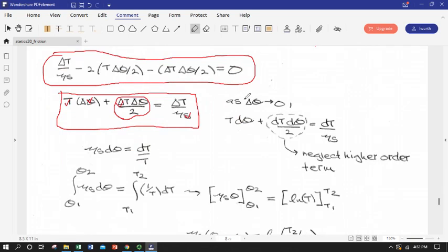So I'm going to take the limit of this expression that I just boxed, and I'm going to look at what it turns into in the limit as delta theta goes to 0 and becomes d theta, an infinitely small angle element. Well, the first thing that happens is I replace all the delta thetas with d thetas, and my kind of finite but very small change in tension is going to become a differential, an infinitely small change in tension that results from all this, and we're going to see that over here. Mu sub s is a constant regardless of what we do, and we're going to have another d theta here.